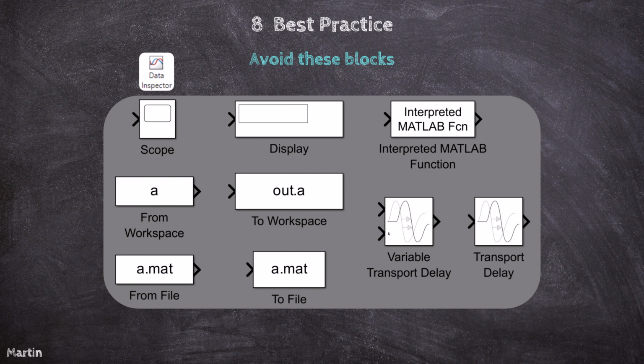Some Simulink blocks rely on interpreted code, which can negatively impact simulation runtime performance, especially in the default Accelerator mode. When a model contains a significant number of these blocks, the performance benefits of running in Accelerator mode may be minimal. Let's use the Scope block as an example to demonstrate this.